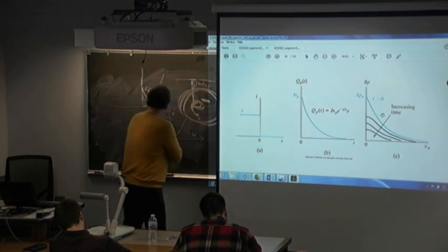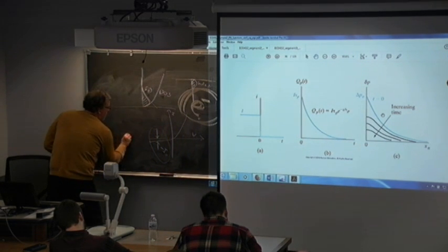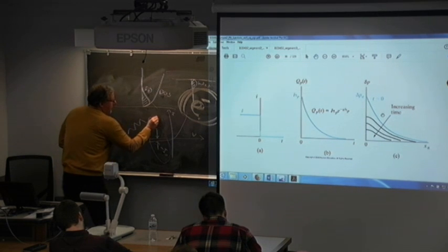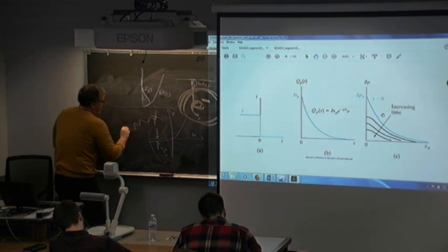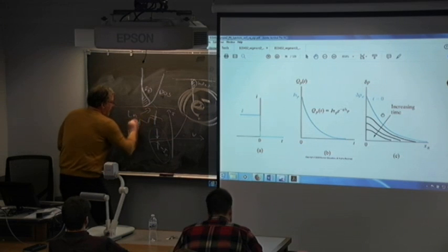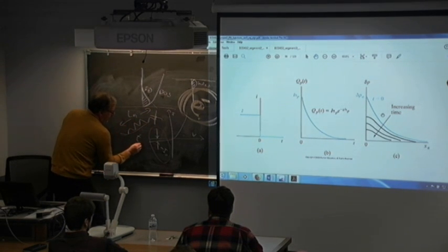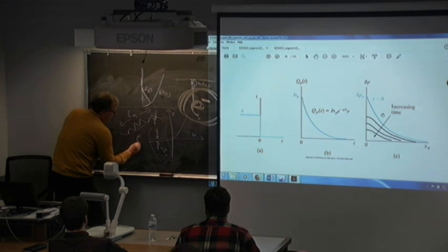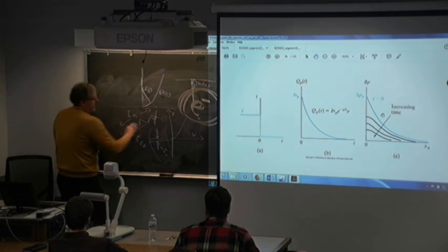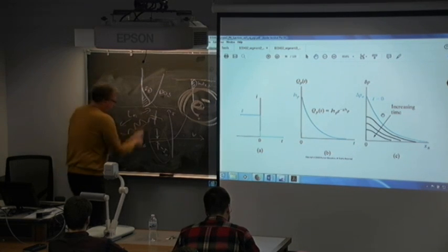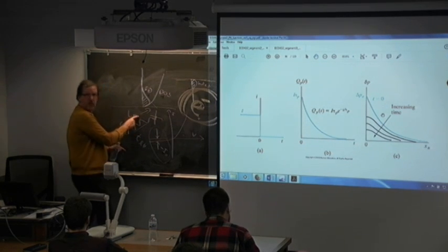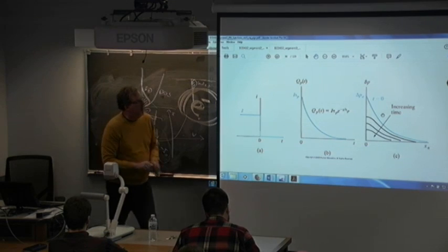So a carrier will move in a drunkard's walk, and then it will recombine. So you could think about it as diffusion length, or how long it took to get there, the diffusion time, the time constant. So it's either the distance or the time. When we're talking about diffusion length, we're also thinking about the average time.